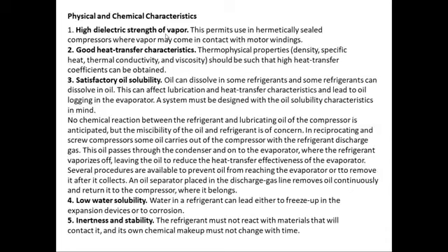The motor's winding is open into the lubricating oil to keep it cooler, and the refrigerant is also entering there. So it should have a high dielectric strength of vapor. Otherwise, it will react with the open winding of the compressor motor, and that will be damaging for the motor. So that's why it should have high dielectric strength. It should not react with the current or the circuitry inside the motor.